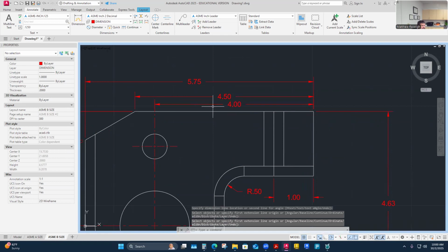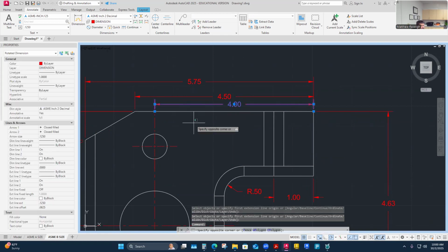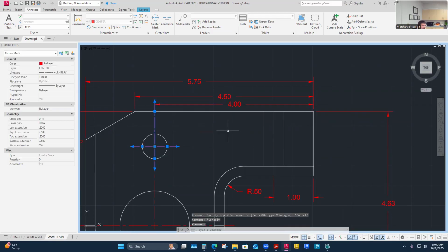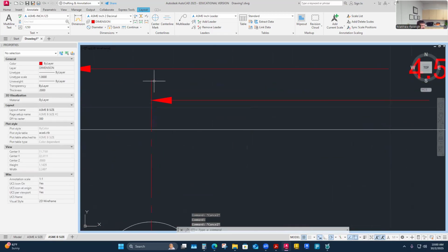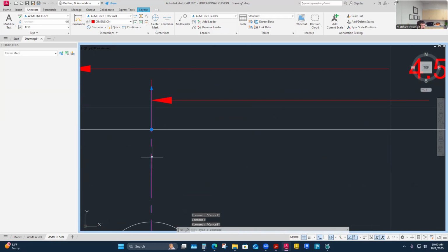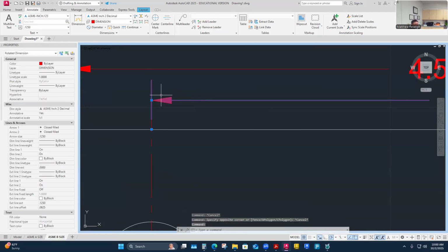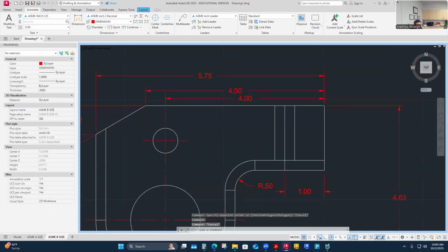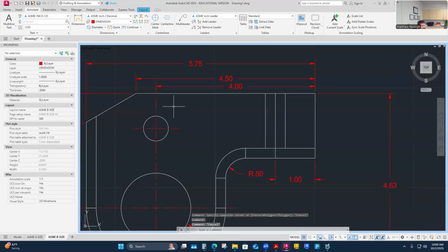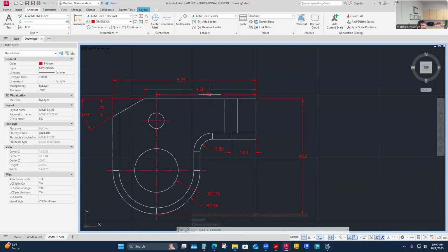That's one location, with the center line overlapping the extension line, which I'm totally happy with, unless maybe it hangs out too much like that. Like I can tell that this one, oh no, it's okay. The dimension is still longer. The dimension extension above the dimension line is a little bit longer, so that's good. And then I just need the other. So that is functioning. That's doing double work. It's doing the locating for this hole, which I haven't even worried about yet, but it's doing the locating for this hole as well. And I'm showing that through my center lines being continuous.